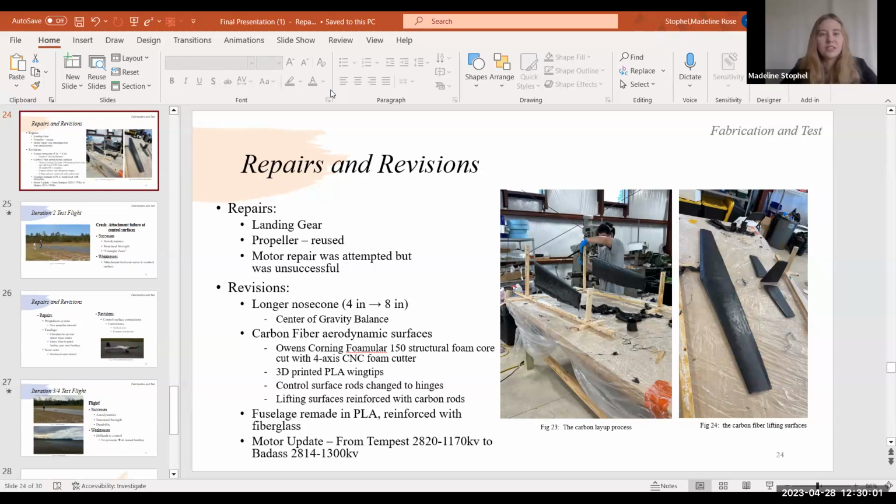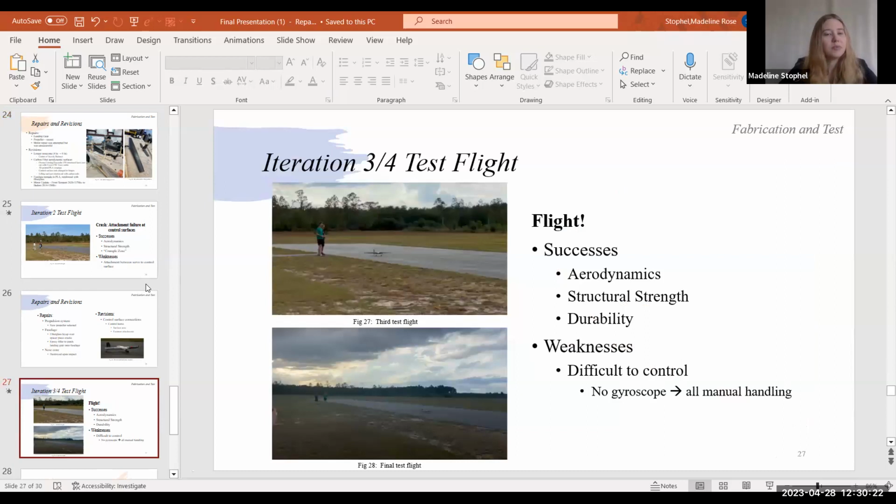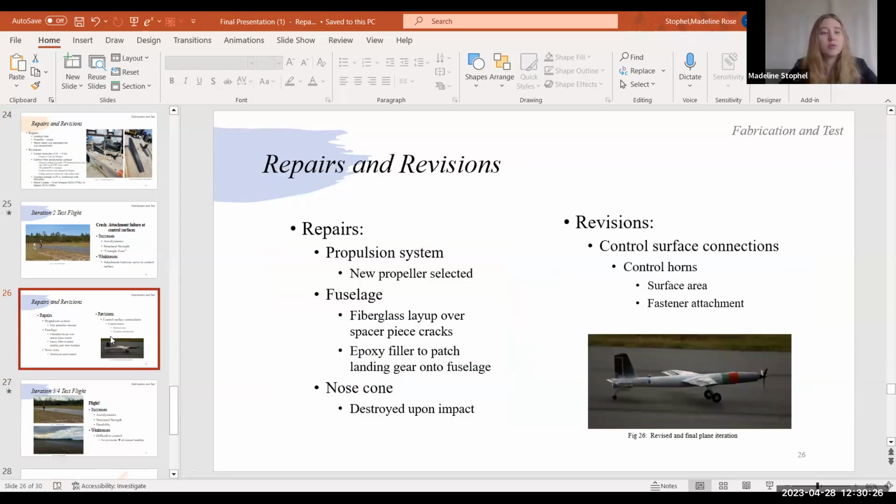Some other tests we did quickly run: we always ended up testing our taxiing, and obviously all our control surfaces. We ran a taxi test, on video, the night before our first test, which was very exciting. And another test that we did, last minute, was before our third test flight. We did have issues with the motors. We had to switch between the first and the second test flight, but obviously the second one crashed as well.